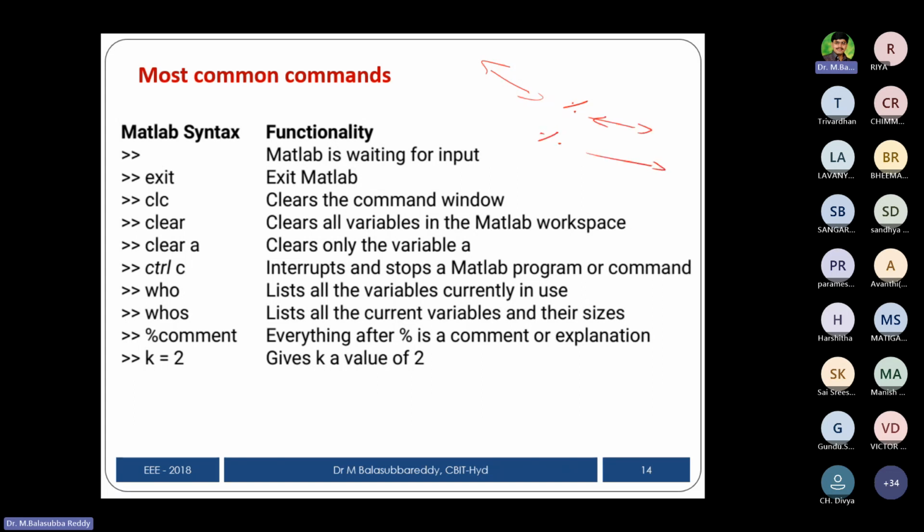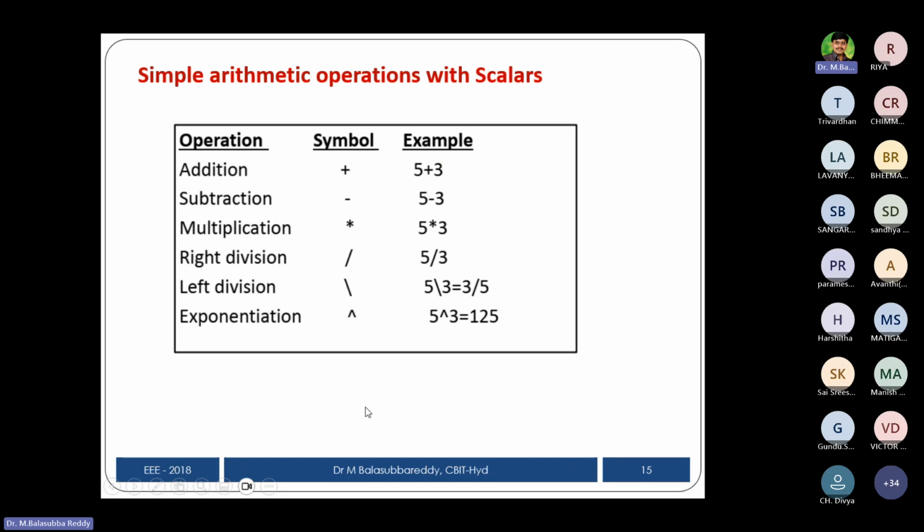So with the percentage symbol, the cursor will not go inside of this. It will go elsewhere, meaning it will not enter that line. It is a comment, only for your reference. Everything after the percentage symbol will not be executed. It won't consider anything. And k is equal to 0, or a is equal to 2, or b is equal to something, those numerical values you can provide. And these are some of the simple arithmetic operations in MATLAB.